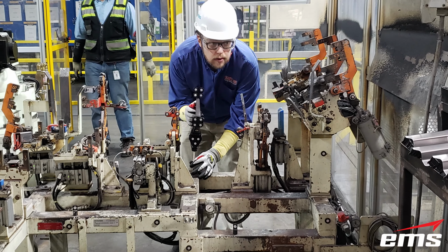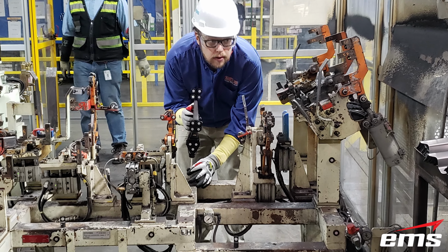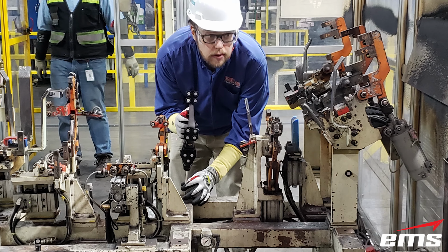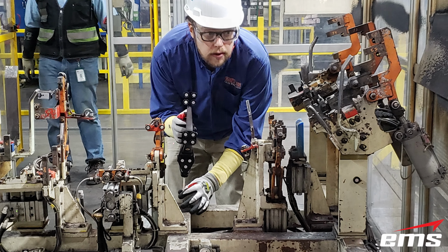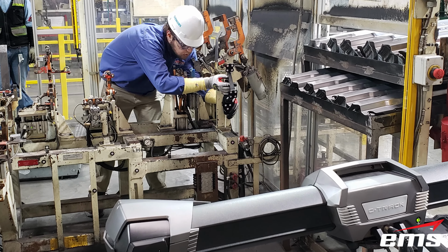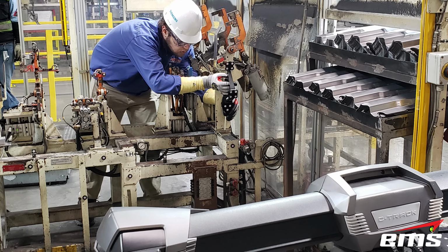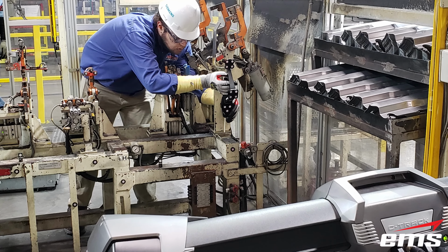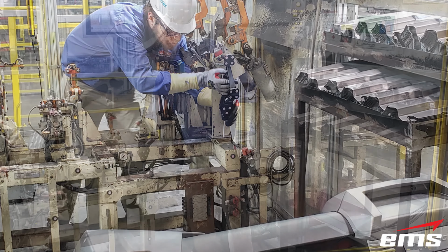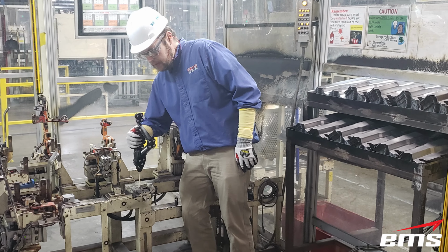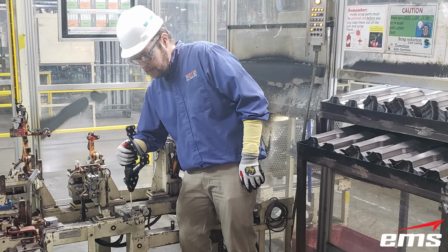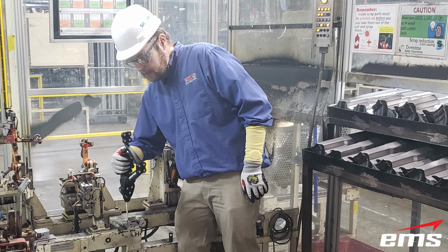So to get started, the first step in the process is to set up a coordinate system to start doing the inspection. And typically a fixture is going to have tooling spheres, pads, holes, some way of positioning a coordinate system or a datum system, and that could be in a world coordinate system. Typically for automotive, they use a Cartesian coordinate system, but you need to set that up. And to do that, we're going around on the fixture and probing these key points as they're called out in the drawing, so that then all of our measurements are related to that coordinate or datum system.